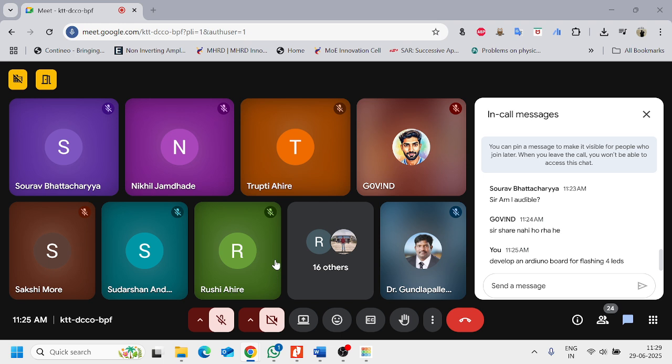In case, we can also say else, the elements here, and then here in the bottom, we will write the commands. Now we can say if, okay. So this time, by the way, we were writing only digital write, right? This time we will do digital read. This time we're gonna read the value.